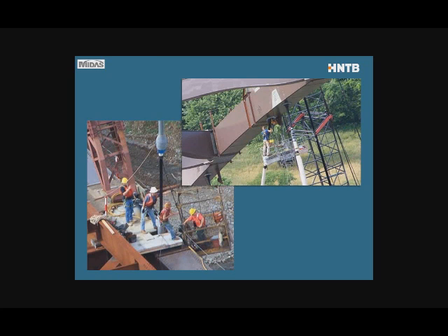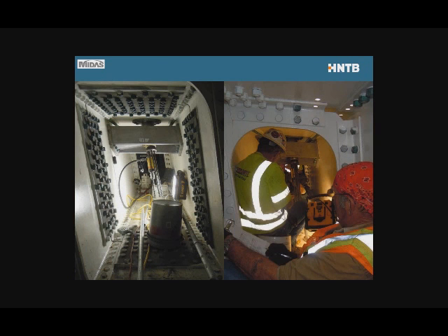The strand is pulled up inside the pipe, and then a worker inserts the strand through the arch rib, through the wedge. Upper wedge is seated, lower strand is stressed. I promised you a picture of a much more constrained site.